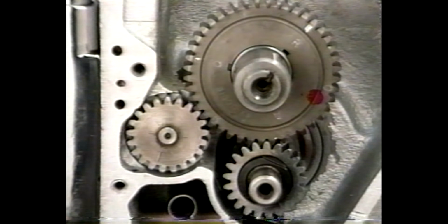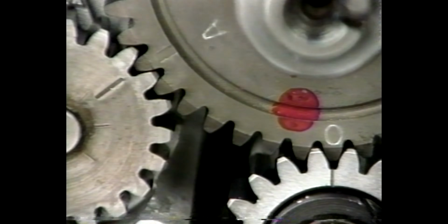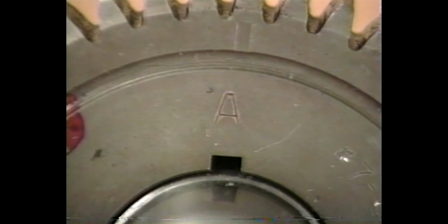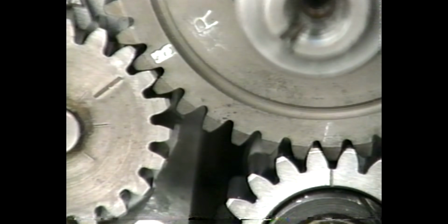When we replace the camshaft back in our engine, the O on the circumference must line up with the pinion gear timing mark, and the slash mark must line up with the breather gear timing mark. If we had chosen the A, or advanced keyway, we would have to line up the corresponding A on the circumference of the drive gear with the timing mark on the pinion gear and the slash with the timing mark on the oil breather gear.